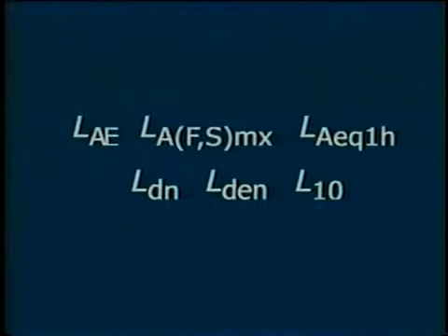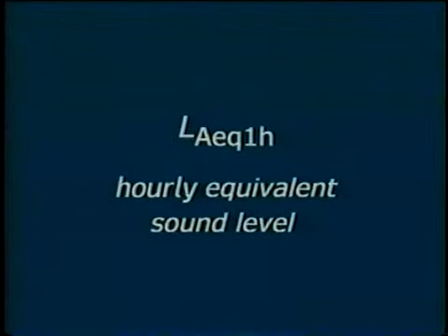While all of these A-weighted noise descriptors can be applied to highway traffic noise, the LAEQ1H and L10 are most often used for traffic noise analysis. LAEQ1H, called the hourly equivalent sound level, is essentially the average A-weighted sound level occurring during a 1-hour period.